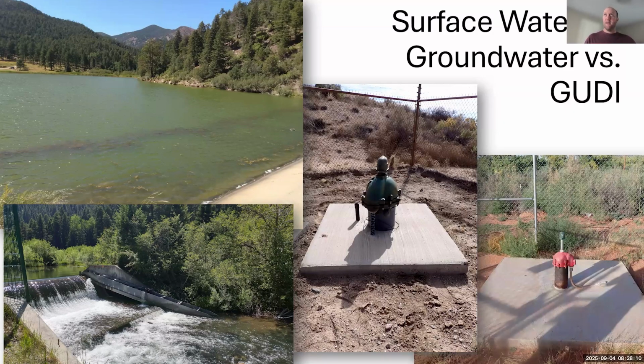And then the last one is abbreviated to GUDI or GUIDISI or all kinds of different acronyms, but basically what it is, is groundwater under the direct influence of surface water. So I'm going to talk about that a little more later, but essentially it's a well that is sucking up water that's in close proximity to a stream. So in this picture, you can see a bunch of green vegetation. There's probably a stream right there. And so this well, it's sucking up groundwater, but essentially it is just taking water from that stream. It's going through a little bit of ground through the earth and then it's getting sucked up right away. So those are our three main categories when we're talking about the sources of drinking water.